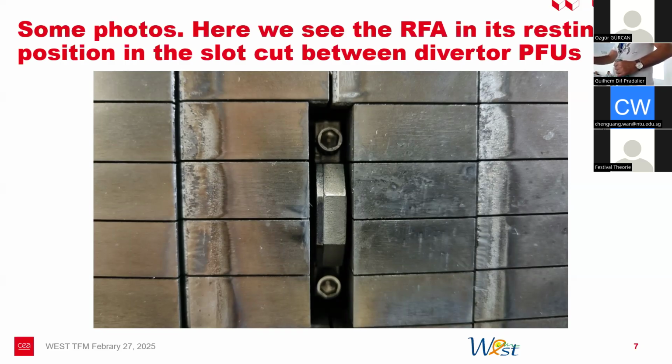So any block that has a sharp edge, due to assembly tolerances, will be blasted by this flux, and the leading edges can melt, and they do sometimes. So all the blocks are beveled by 1 degree in the toroidal direction to protect the leading edges.